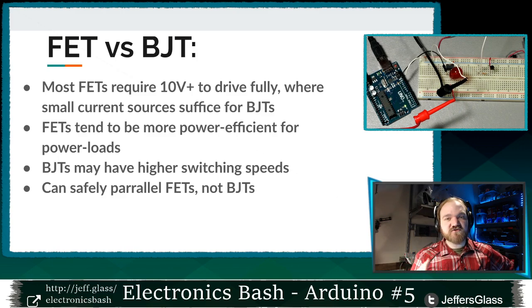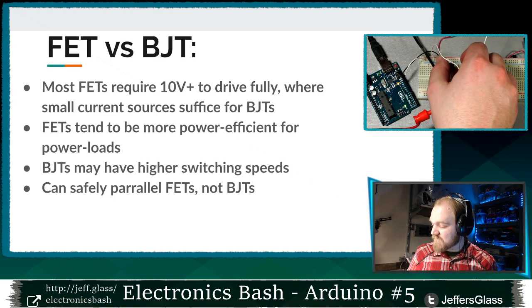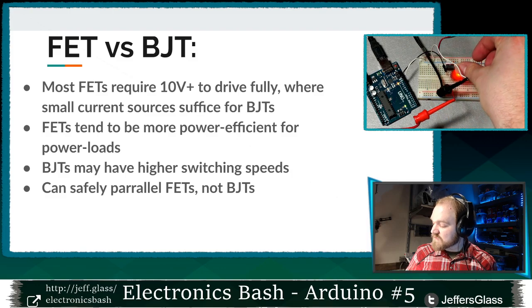FETs, because they reduce their resistance so much when you get these high drive levels on the gate, tend to be more power efficient for driving large loads. So once we're talking in terms of hundreds of milliamps to amps to tens of amps, you can drive them to having such low resistances that they are going to have much less heat losses.